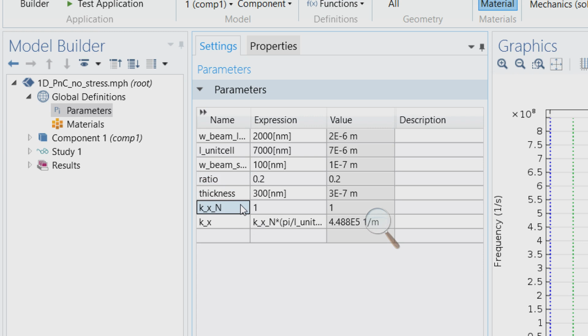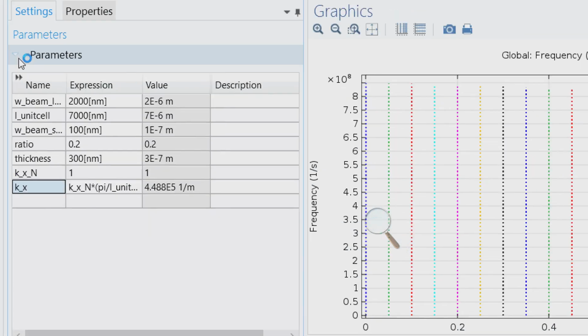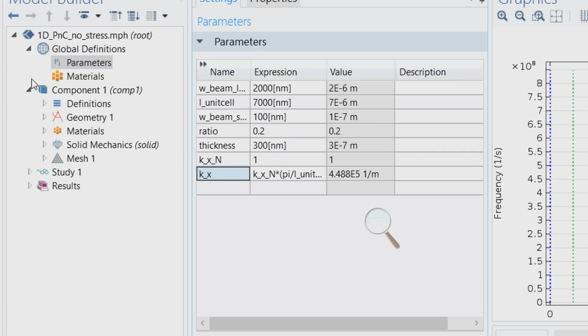And in the plane geometry, what do I have? I have the large section. If I build the selected part, sorry, I named them the opposite way. So it's the small section here, and for the other one, it's this one. And there's a trick you can always do. If your structure has a symmetry, I put a mirror in here, as you can see, and then I just mirror my structure.